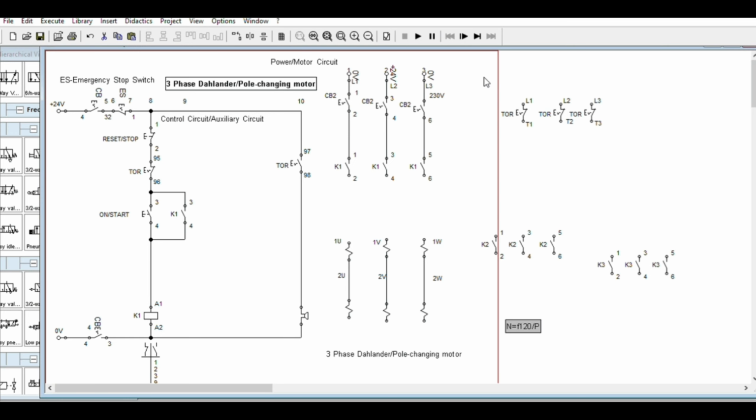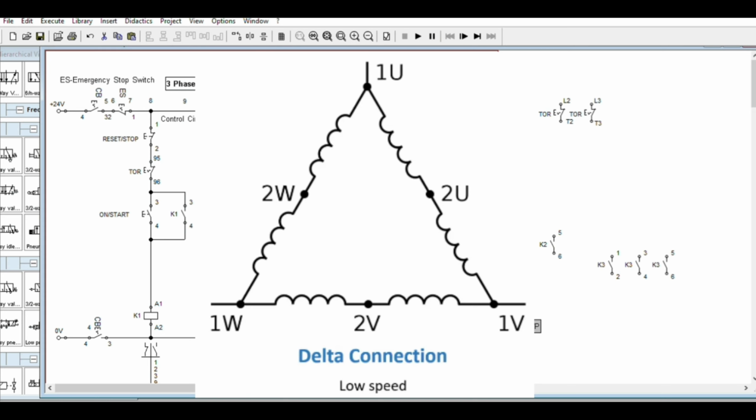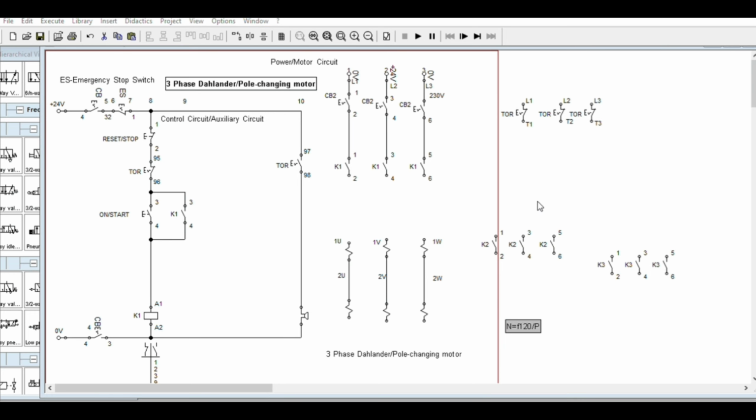A basic small motor, 24 slots, 36 slots, maybe from 1 horsepower up to 5 horsepower. The default connection here is series delta based on the US standard. This is just labeled 1, 2, 3, 4, 5, 6. Only 6 terminals are brought out of the motor's terminal box. We can convert this into T1, T2, T3, T4, T5, T6. This is the IEC and European standard.